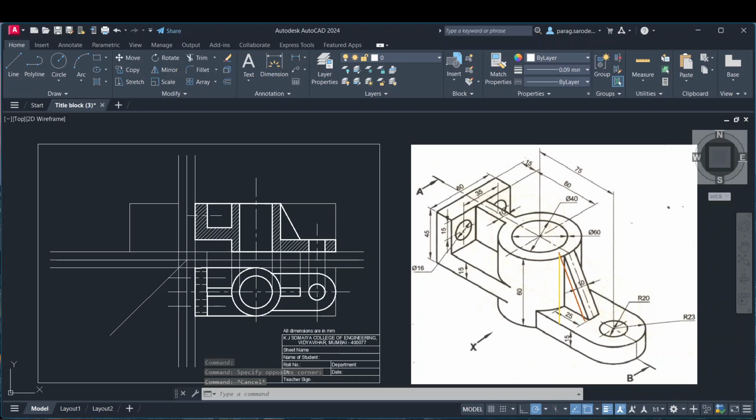Now, while drawing the right hand side view, what is the first thing that we see? This is the portion that we see first. Then this is the rib that we see, which needed to be drawn as rectangle, and then we see this cylinder which will be observed as a rectangle. And one more thing we should observe here is that the figure is symmetric, right? So we'll draw a center line first to indicate the symmetricity in this way.